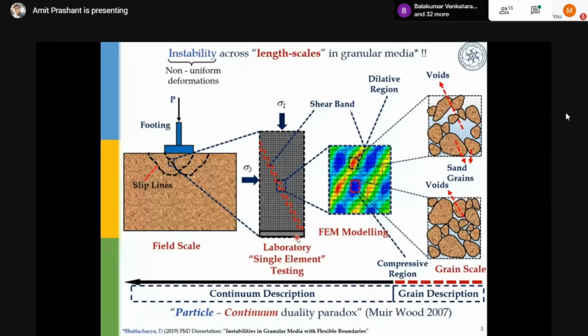So that means under undrained condition also, when we assume there is no flow of water, actually there is a flow of water, but it is local. And as you can see on the particle scale, that is possible as well, because as the particles deform, they collapse, they form new blocks, and the water will be moving locally from one zone to another zone.